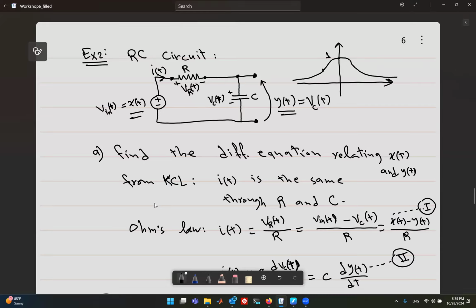And at some point here, we have that cutoff frequency. This is minus omega c, and we consider this as the pass band of the filter. Signals having frequency higher than omega c will be attenuated by a high factor, and we assume that they didn't pass the filter and they are filtered out.